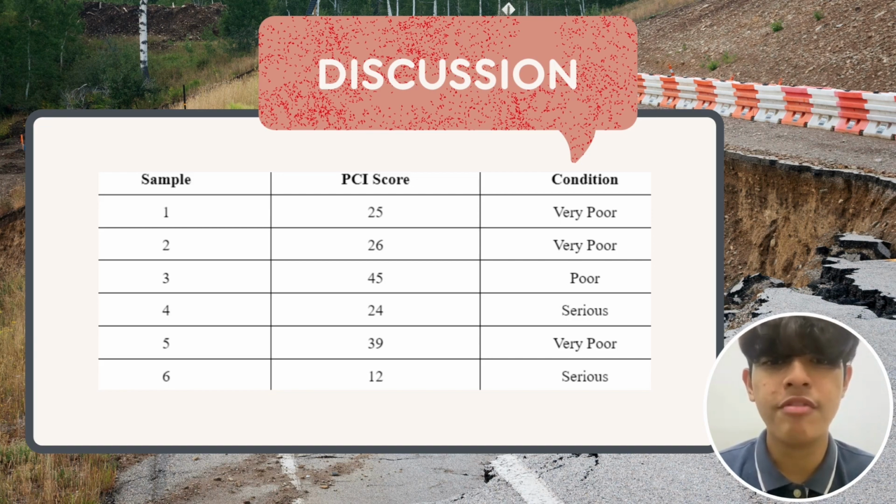Throughout the study, we found out Jalan Parit Jelutong is considered as the road that connects to the main road. Therefore, we strongly suggest that the relevant authorities, which is the Public Works Department (JKR), can work together with local authorities in Parit Raja to check and repair this road. Maintenance is constantly needed until the PCI value of the road can sustain above 70, which is the grade of satisfactory and good. Only with that, the safety of the road user can be guaranteed and the accident rate of Malaysia could be reduced.